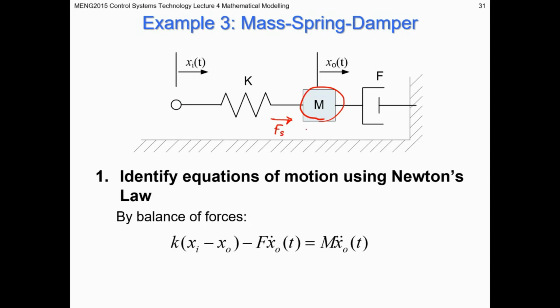So you have a spring force, that we'll call Fs, acting to accelerate the mass in a positive direction, and you've got a resistive force which is coming from the damper. If we are accelerating the mass in the positive direction, the damping force is going to be a retarding force on the mass's motion. Right, so that's what we've got represented here.